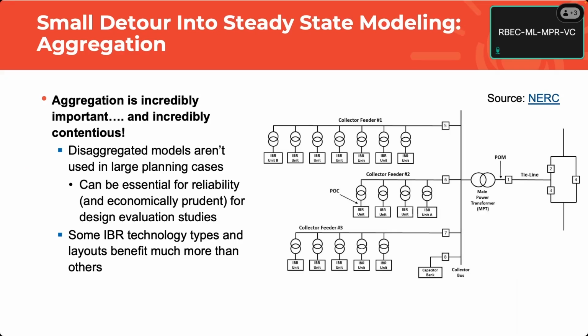For wind, a lot of times after you get close to 5% and go towards ride through, in the normal operation range at the 10% range, you get degraded reactive power capability as your voltage gets worse one way or the other. So for example, if it's 0.91 at the farthest turbine, that turbine has a significantly different reactive power capability than the one right next to the substation, which means it's probably significantly less.